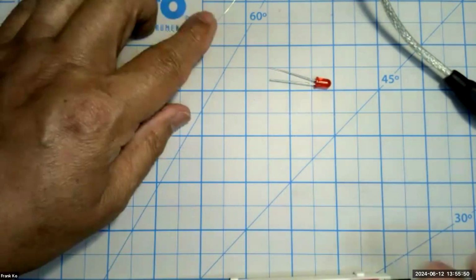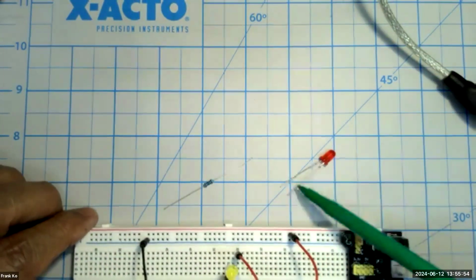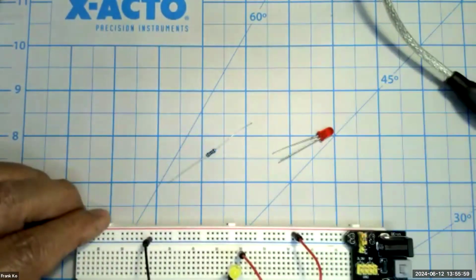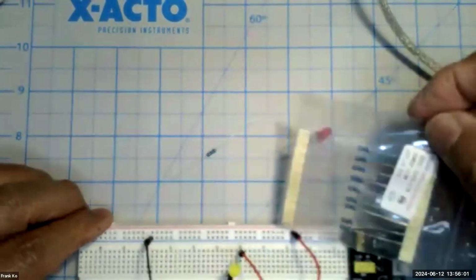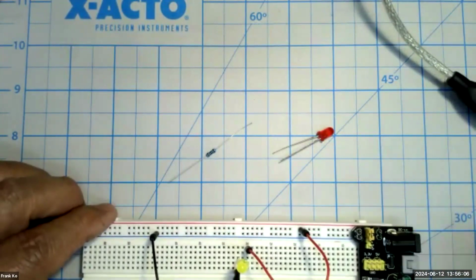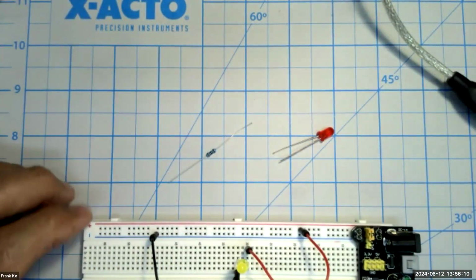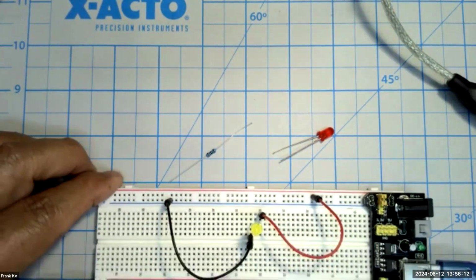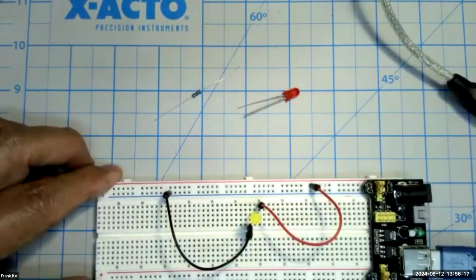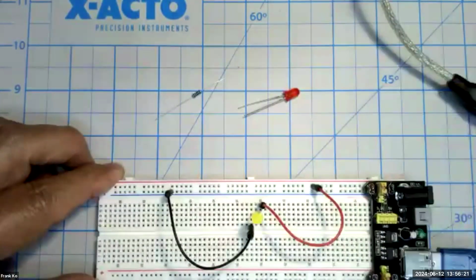One of the most common reasons is some kind of sticky residue that may be on the ends of your components, especially the resistors, since they come off of masking tape like so. So we said you want to clean the ends of your resistor wires. The other reason could be that the tie points themselves, these points, may be a little fussy. And if they are, we're going to do something called frogging. What is frogging? Frogging is like your frog leapfrog. It'll jump from one to another to another.